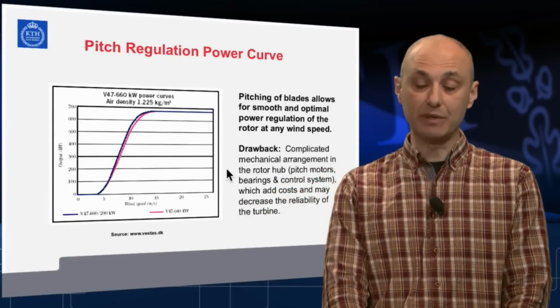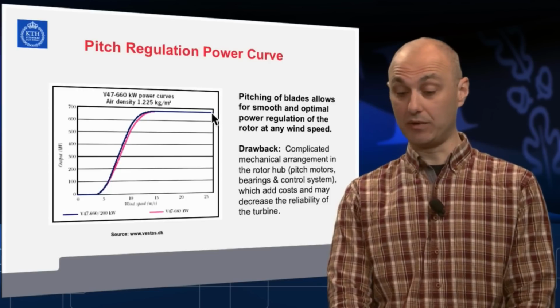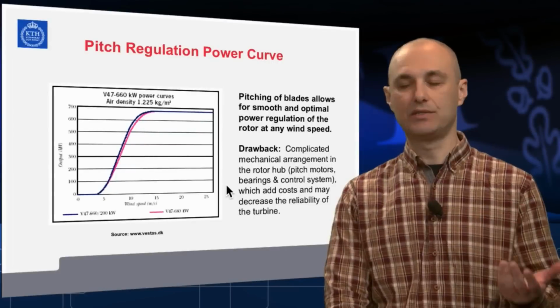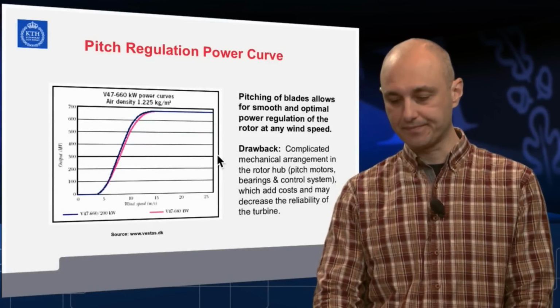But the achievements are wonderful. Pitching, or the pitch regulation, is able to deliver very nice performance in the low wind spectrum. You can start pitching already from the cut-in speed, and then you're able to support and sustain a very nicely stable power output in the high wind spectrum. You can also play, if you would like, with the cut-off speed pitches. As soon as the blade can pitch, it allows you to do everything.